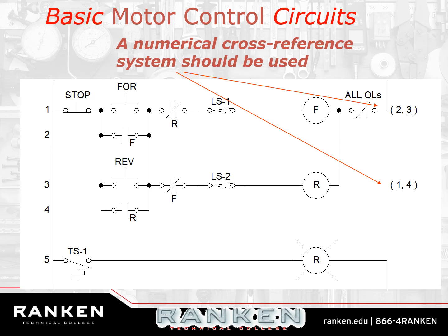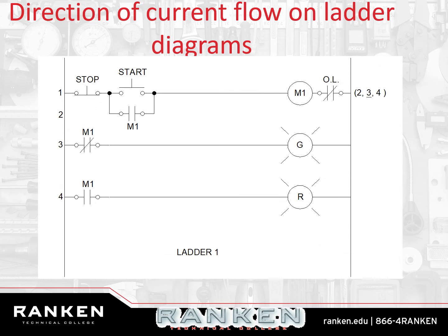If I know that coil is getting energy and those contacts are pulling in, chances are the thing's working, right? Now it's a problem with the motor. Everything else is good. We're going to talk about that later on when we talk about troubleshooting.